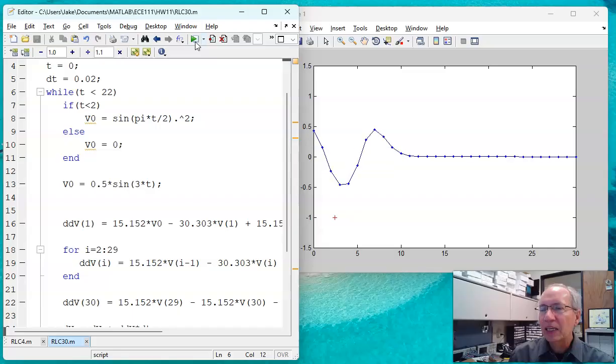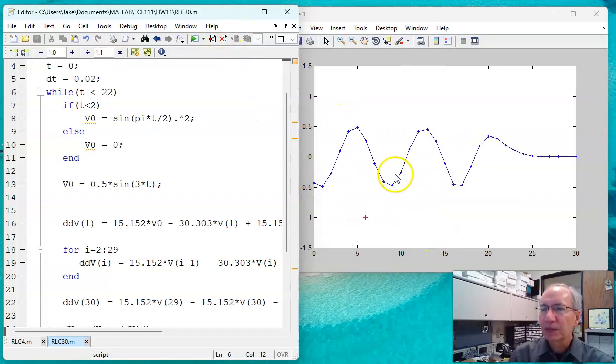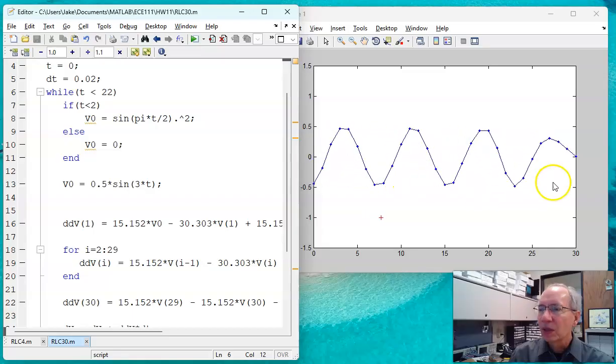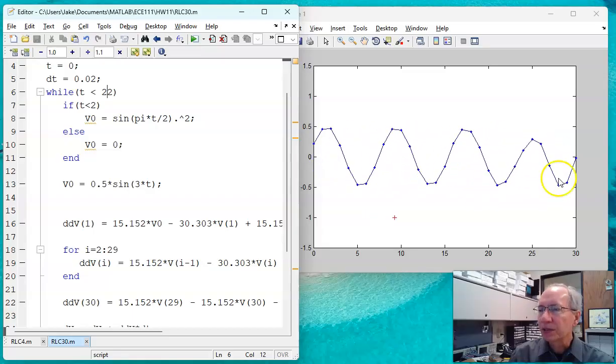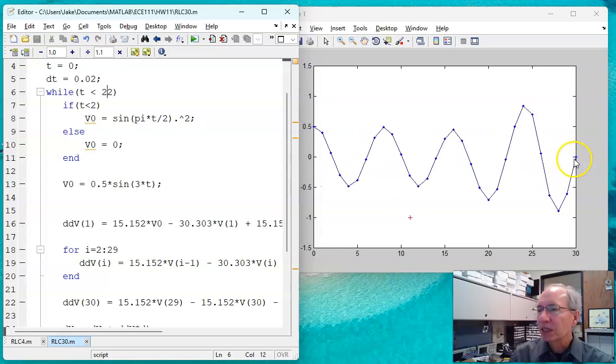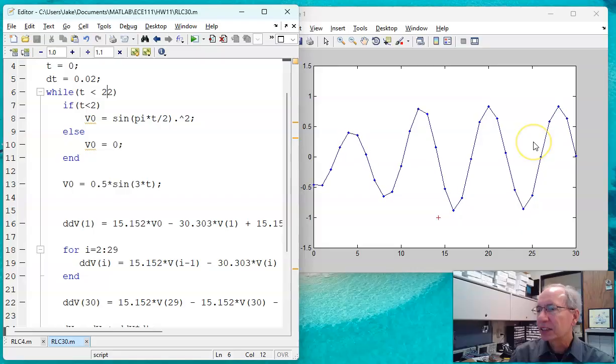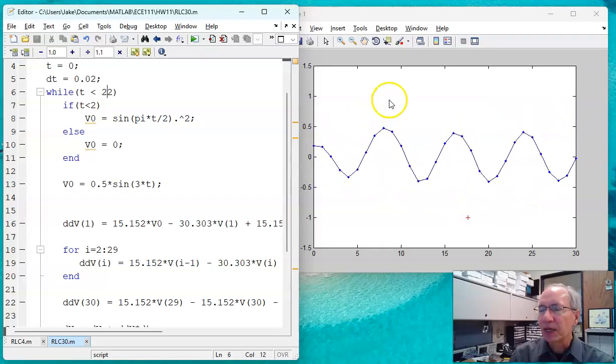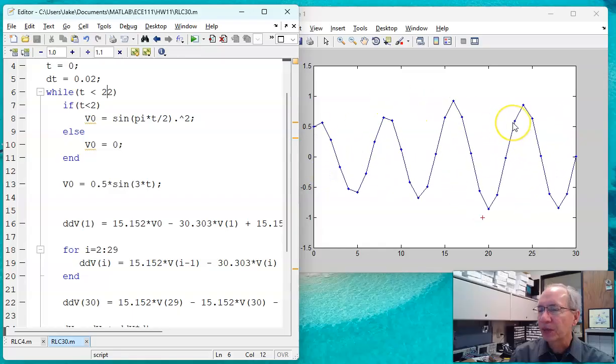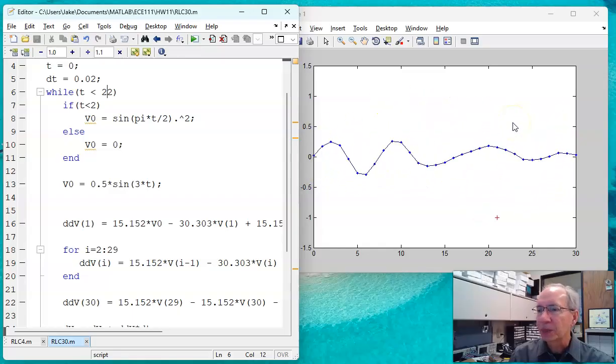If I had a circuit and I send the signal down it going plus or minus 0.5, and I have a negative reflection, the right endpoint just barely moves. I've got a negative wave coming back, another wave going forward. I get these standing waves, just like I had before. Now the input used to be 0.5. The standing waves have an amplitude of 1 already. That large voltage can break components.